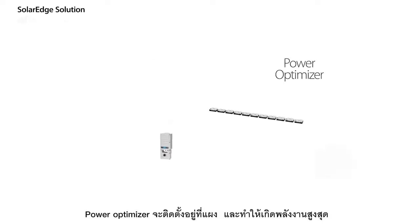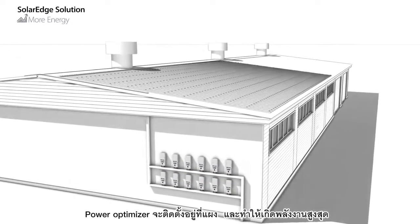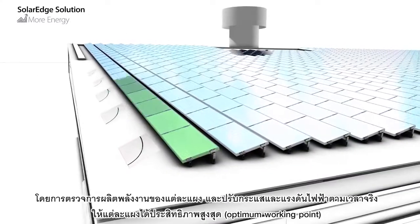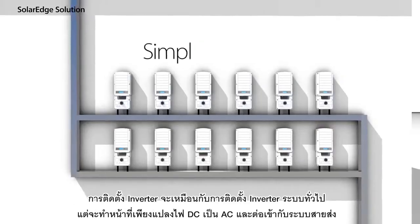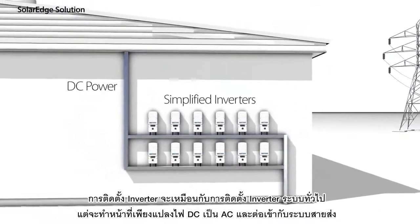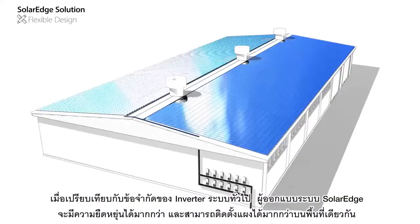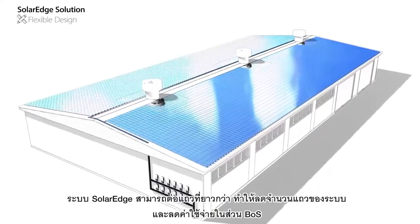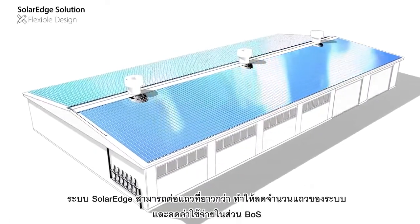The power optimizers are located on the panels, turning them into intelligent panels. These power optimizers maximize system output by providing panel-level tracking and real-time adjustments of current and voltage to the optimal working point of each panel. The simplified inverter is installed similarly to a traditional string inverter, but it is only responsible for DC to AC inversion and grid connection. In comparison to the limited design of string inverters, designers of SolarEdge commercial systems enjoy great flexibility and are able to fit more panels in a given space.